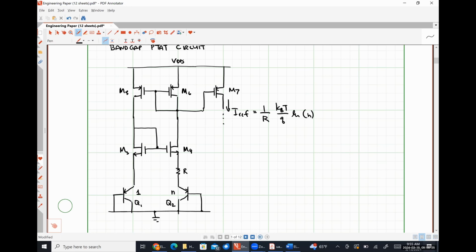Now, this provides a relatively stable biasing current. However, the footprint, and by that I mean the physical space that it occupies on a chip, is actually too large for it to be useful. And let me rephrase that. You don't want to have to do this a whole bunch of times on every single chip for every circuit that needs a current source to bias them. And that's where current mirrors come in.